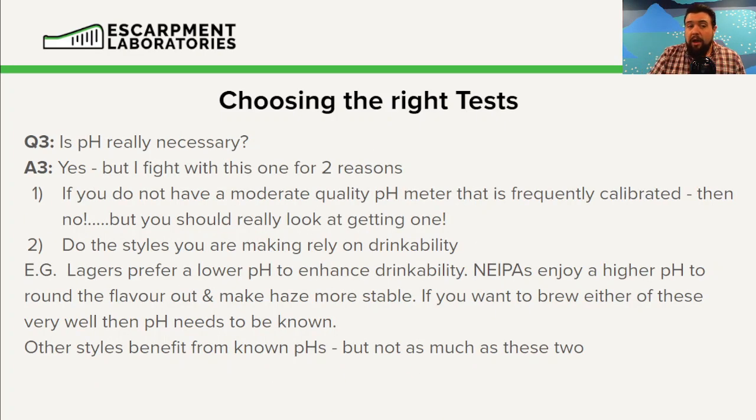Number 3, is pH really necessary? I get this one a lot, where I go into a brewery and I realize they're having pH issues, but they don't have a pH meter. So I would argue that the answer to this is yes, pH is very important, but I fight with this answer for 2 reasons. The first one: if you don't have a moderate quality pH meter that is frequently calibrated, then don't use it. But you should really look at getting a higher quality one.